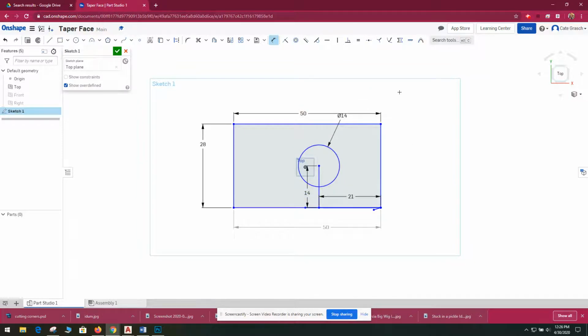Okay. So now I'm going to clean it up a little bit because I want to extrude it. So I'm going to use this trim tool and I'm going to take out this line, and then these other little lines that don't really necessarily need to exist. Okay, go away. Okay. And there's one right here that can go, oops, we don't want that. I will leave it because that's not going to bother our extrusion.